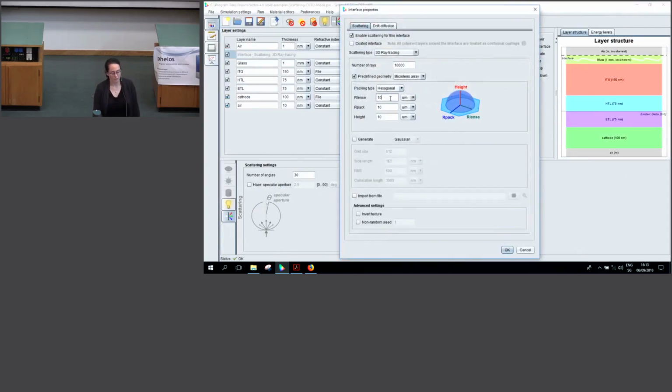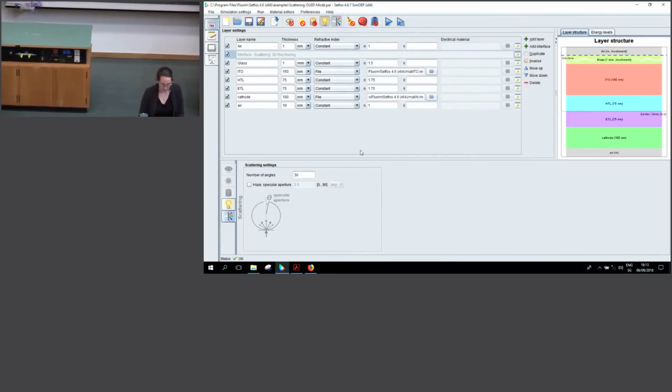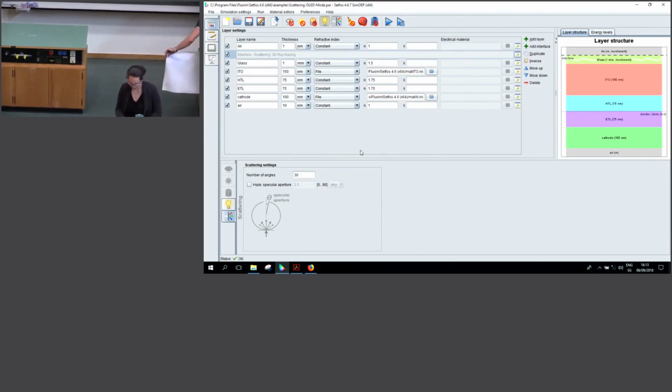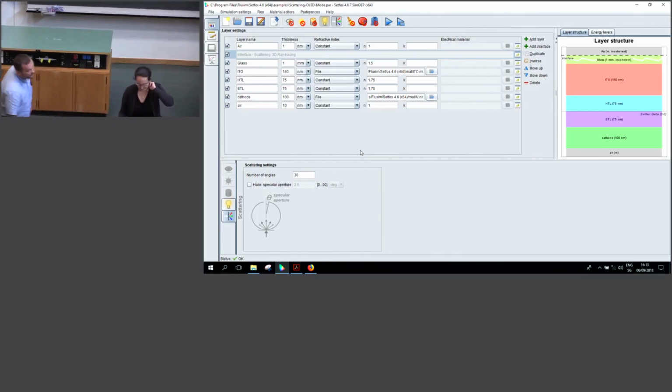Yes, I think you can. If you have parameterized hemispheres, you can optimize this. I would need to double check whether it's possible, but I think so. Do you know? Can we optimize these parameters directly? Yes, the geometry parameters can directly be optimized. So you can sweep the lens parameters and also the OLED stack parameters, and that's one of the key advantages. Instead of optimizing the stack separately from the scatter foil, you can simultaneously sweep scattering parameters and stack parameters.